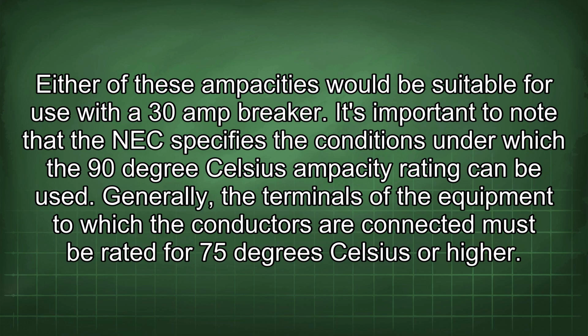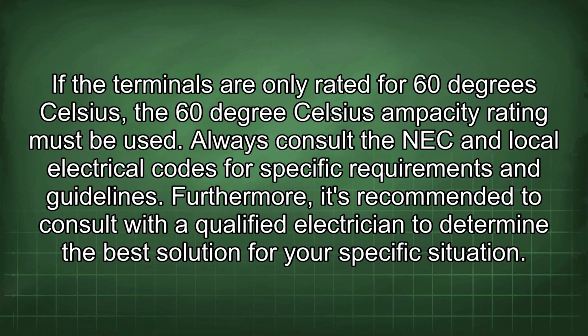It's important to note that the NEC specifies the conditions under which the 90 degrees Celsius ampacity rating can be used. Generally, the terminals of the equipment to which the conductors are connected must be rated for 75 degrees Celsius or higher. If the terminals are only rated for 60 degrees Celsius, the 60 degrees Celsius ampacity rating must be used. Always consult the NEC and local electrical codes for specific requirements and guidelines. Furthermore, it's recommended to consult with a qualified electrician to determine the best solution for your specific situation.